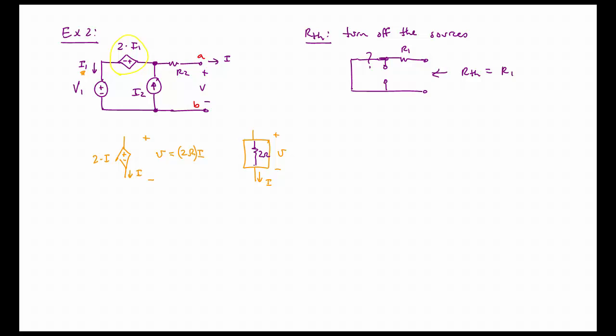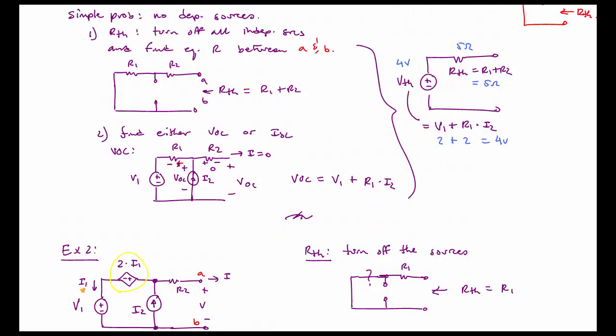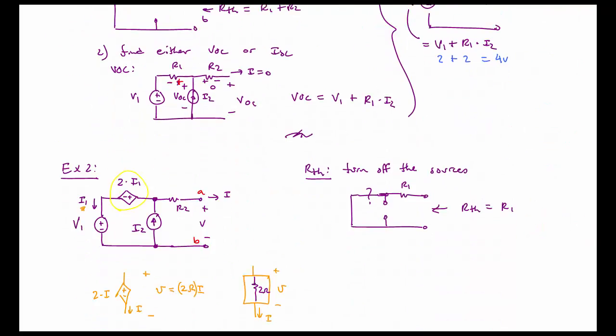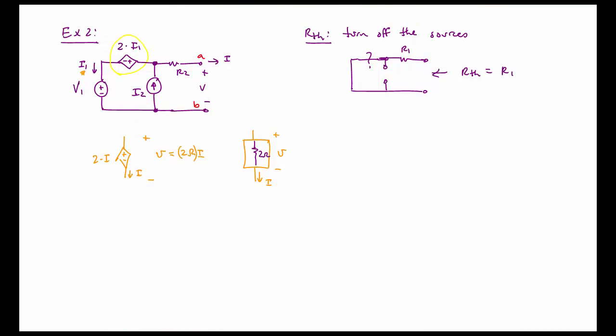So now that we know that this dependent source in this configuration, meaning it is dependent on the current flowing through itself, is actually a resistor in disguise, is it possible, in the example problem we solved when there was a resistor R1, that the Thevenin equivalent resistance is actually just R1? And we have to say, because of what we just discovered here, no.